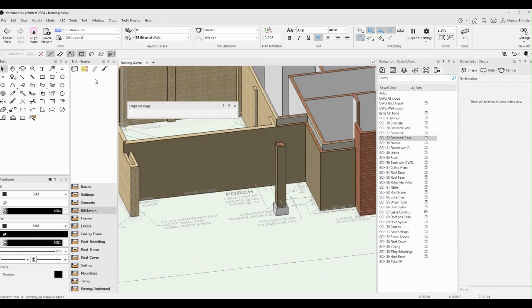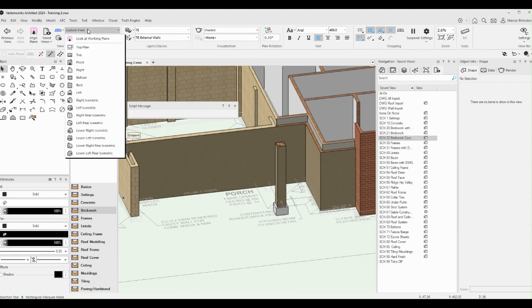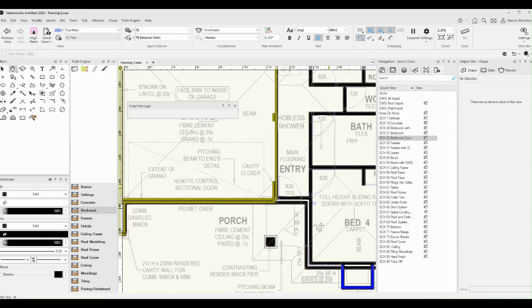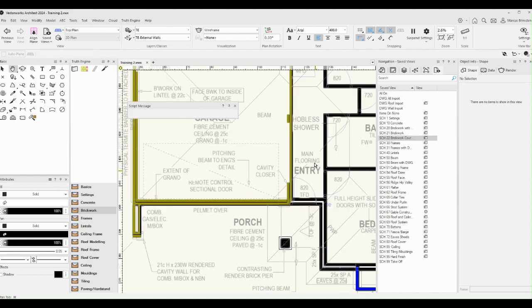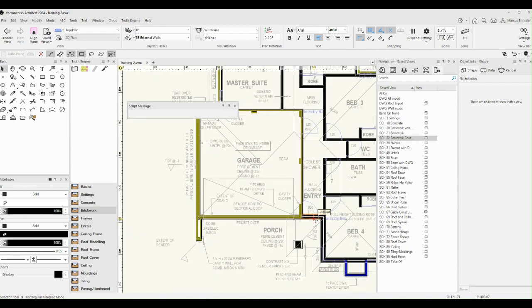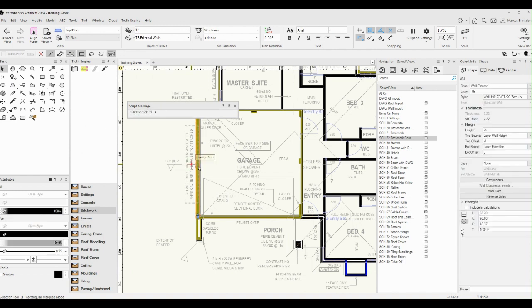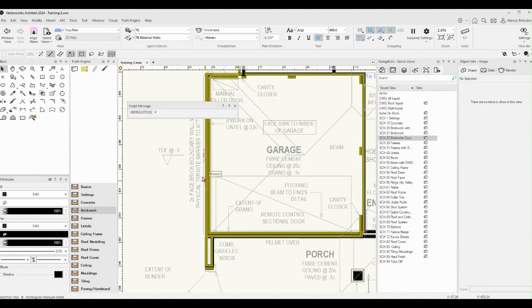So if we go to our plan view now, let's check for any drop footings around the front. So we can see we've got -3 to that wall, and it goes to there. So there's -3 courses through there for a top of footing. So what we're going to do is we'll split that wall there, because I want this part to be a -3, this part to be -2. So run my split tool.